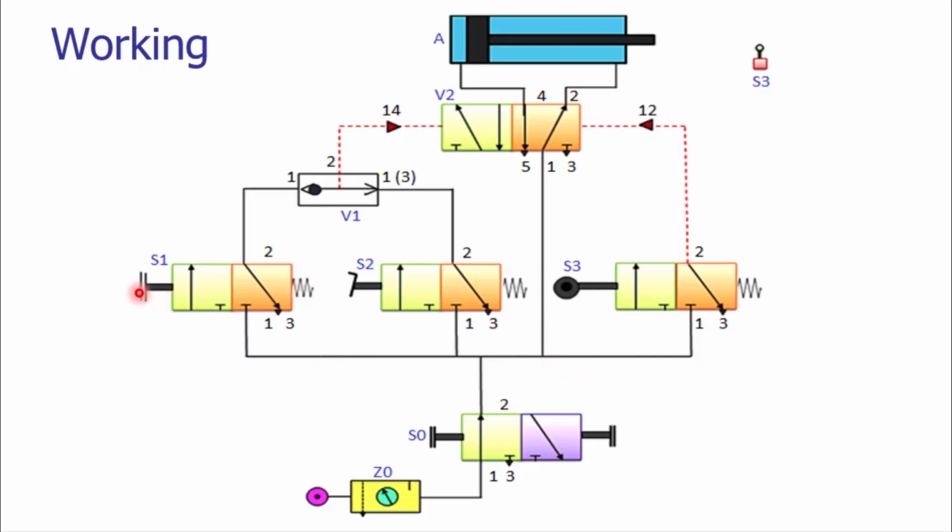So consider the push button is actuated. The default position of the push button valve is this. Here the application port is connected to the vent, and the input port or the power port is shut off. There is no input at this stage. This is spring loaded.